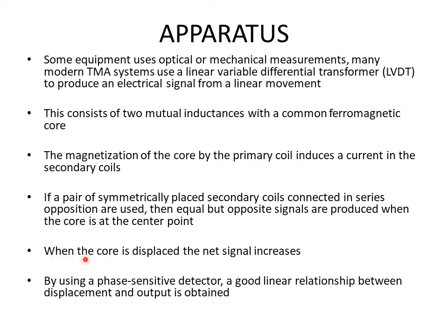When the core is displaced, the net signal increases. By using a phase sensitive detector, which is a detector that detects any change in phase, a good linear relationship between displacement and output is obtained. So we can obtain various moduli in this case.